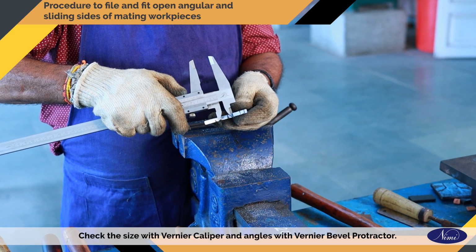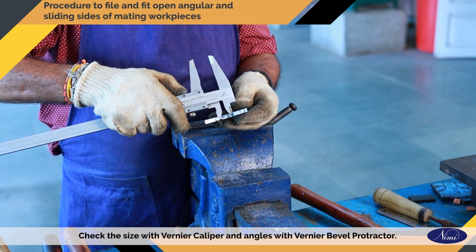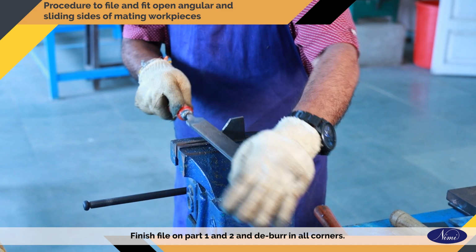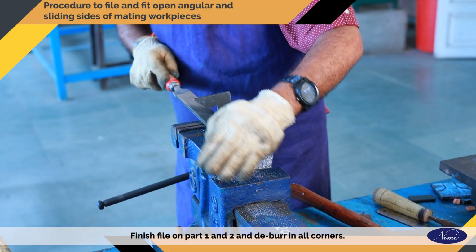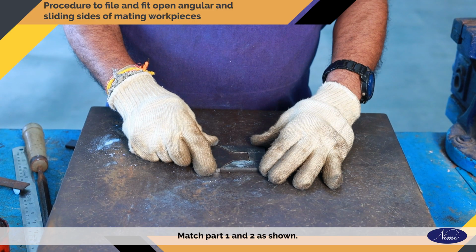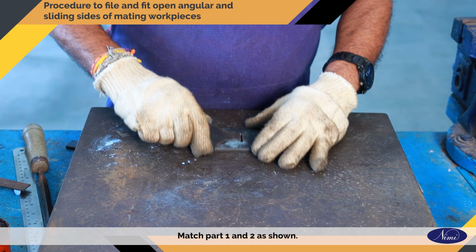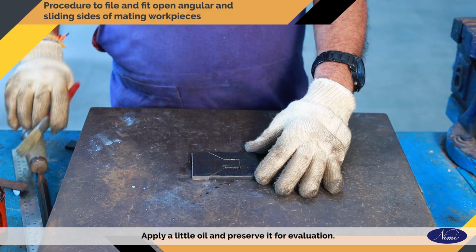Check the size with vernier caliper and angles with vernier bevel protractor. Finish file on part 1 and 2 and deburr all corners. Match part 1 and 2 as shown. Apply a little oil and preserve it for evaluation.